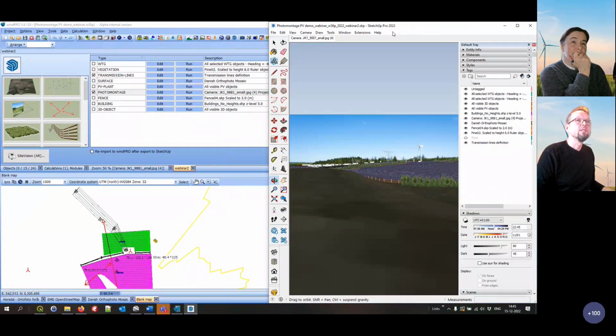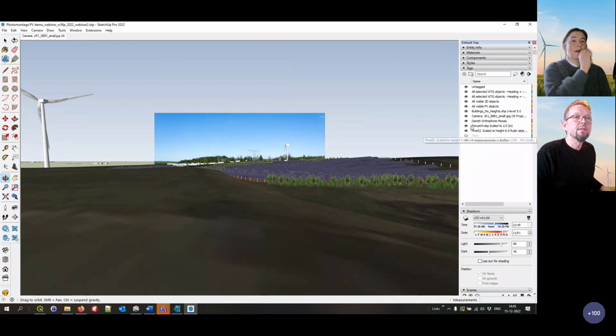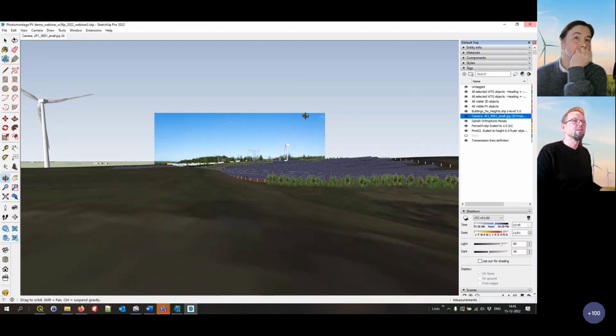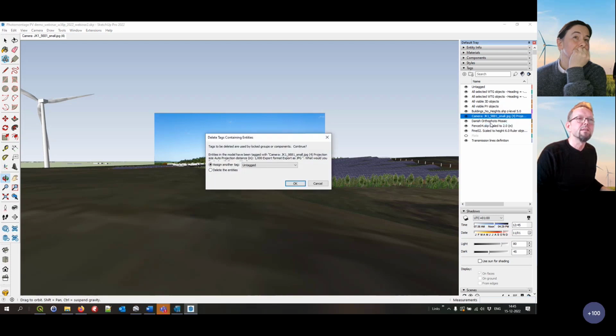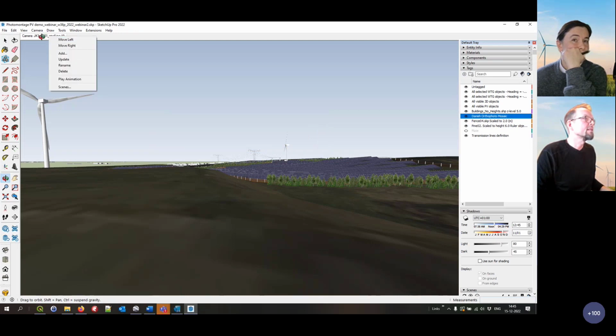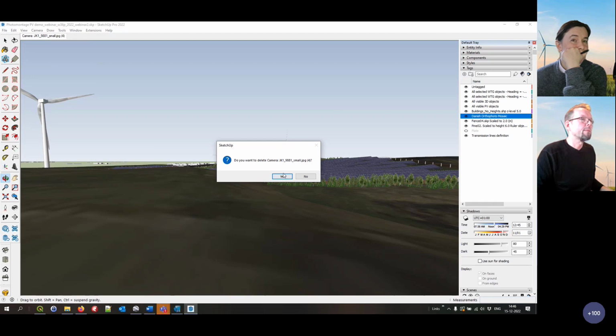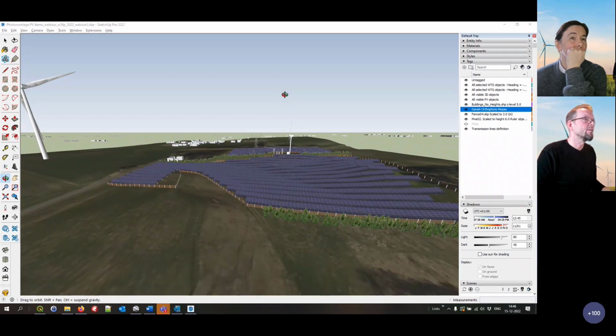And now I'll go back to SketchUp. Okay, I need to redo that, because I just made it once more. It's because when SketchUp is not maximized, when I export it, I export the whole thing as a tiny image, so it's not good. So I made a small error here. I'll delete the layer with the photo on it, and I'll also delete this scene that is defined up here. Right, and then I'll run the exporter once again.